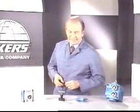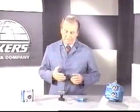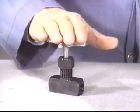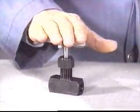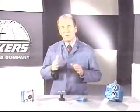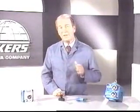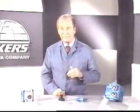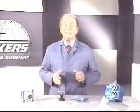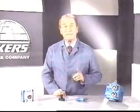Now, let's take a look at a situation where the workload changes. The valve that we've been using up to this point is just a plain old needle valve, something like the faucet on the side of the house. Let's say we have the flow control adjusted for 5 gallons per minute. The other 5 gallons go over the relief valve at its setting. The pressure at the relief valve is 1,000 psi because that's where the valve is set.